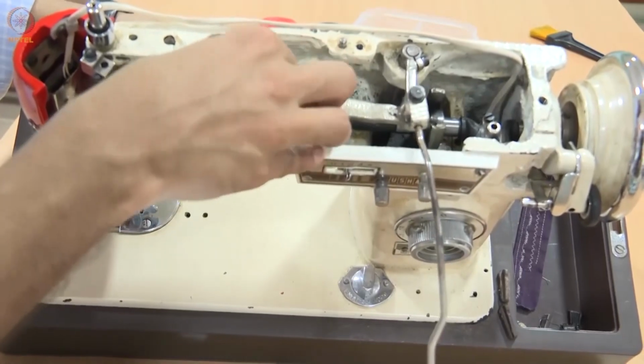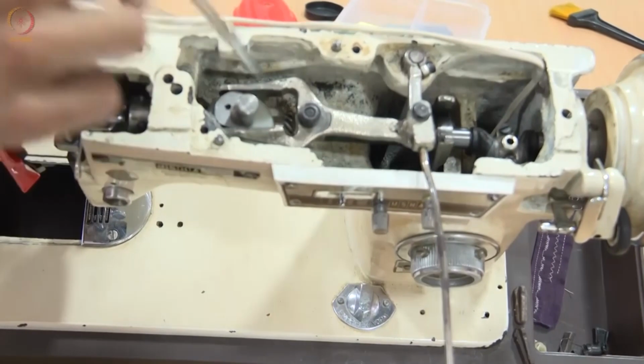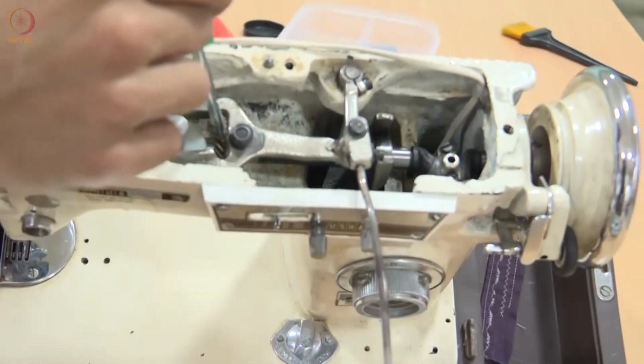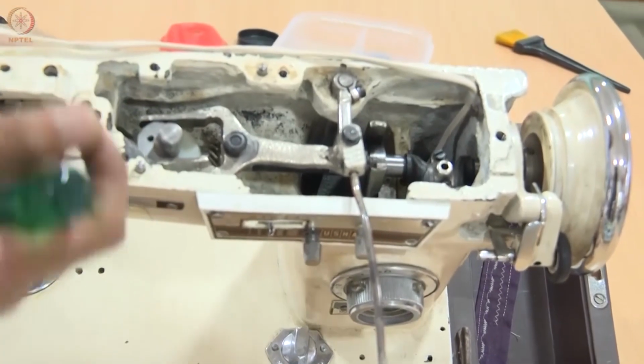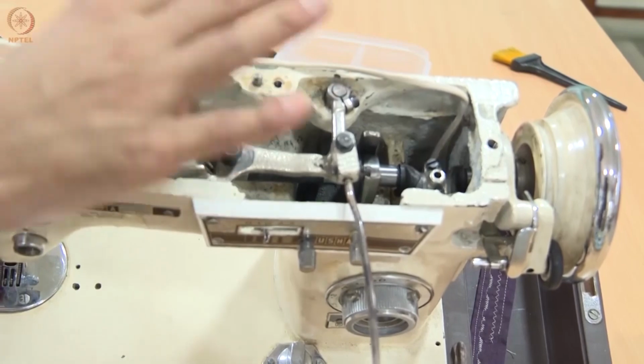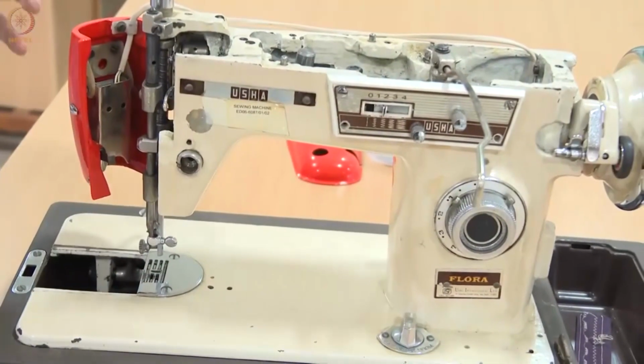So you can see, there is a bevel gear here, right? This is a bevel gear. This is a plastic bevel gear. To reduce noise, one of the gears will be made of a softer material. So this is plastic, this is metal. That shows you different aspects of the mechanism.